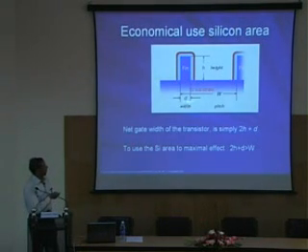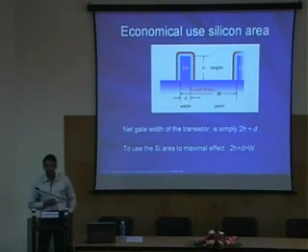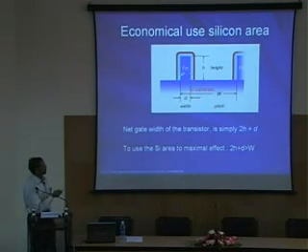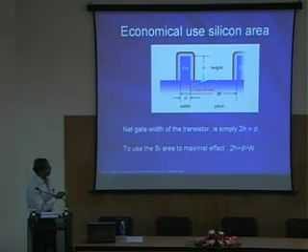Suppose I am making my existing systems using FinFET based MOSFETs. I have shown here the dimensions of the fin for a typical MOSFET. It has a width d and it has a height h, and there is a pitch w, that is the minimum distance that we have to maintain between these two fins. So I have the gate material all around this fin. Now the net gate width is the entire length, which is 2h plus d.